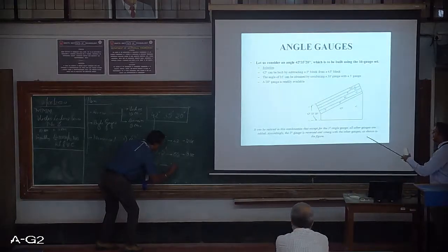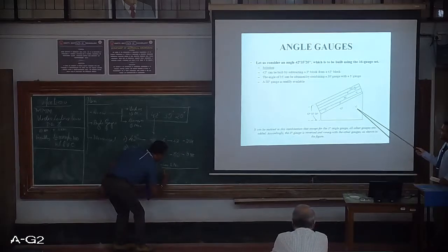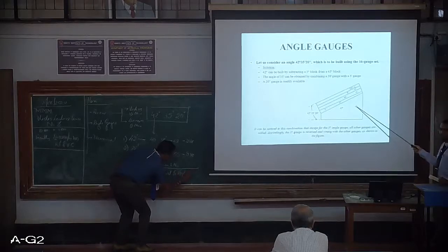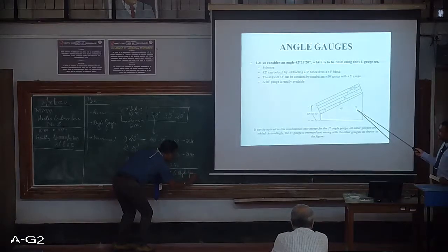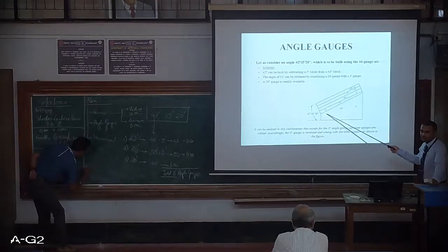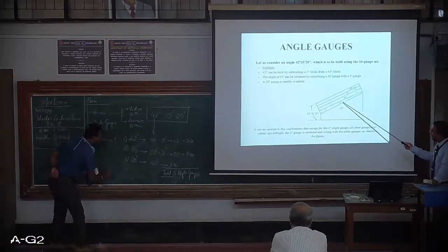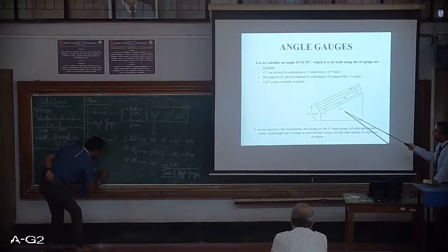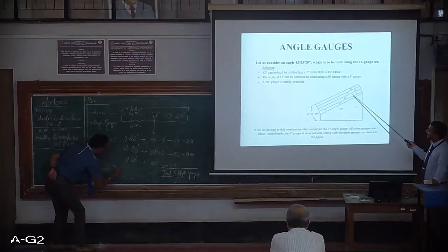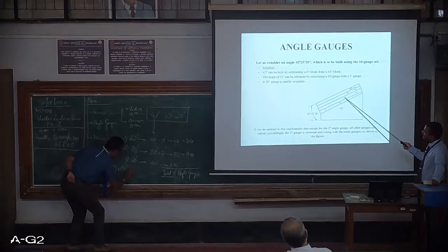You can see over here the symbol on the 45 degree. To the end we have this lesser than symbol, so it is to be set first. Next, observe the symbol over here for the 3 degree angle gauge. It is placed on the opposite side. That means we are subtracting this particular value from the 45 degree. So 45 minus 3 will give you 42 degree.